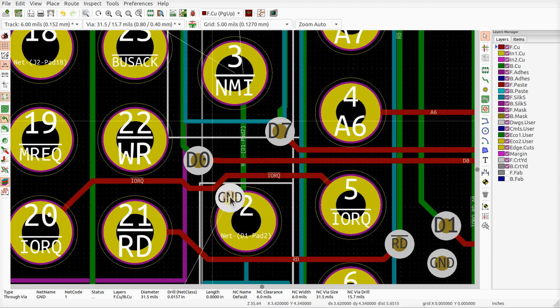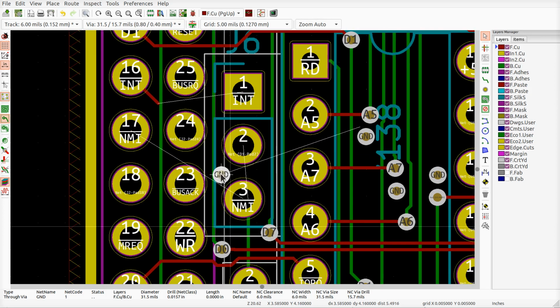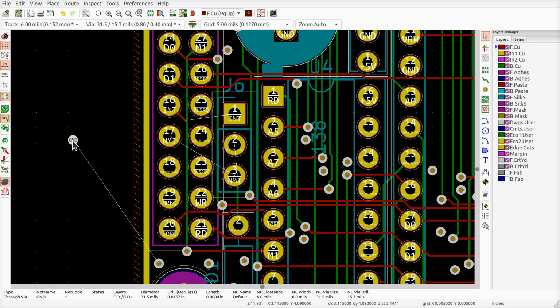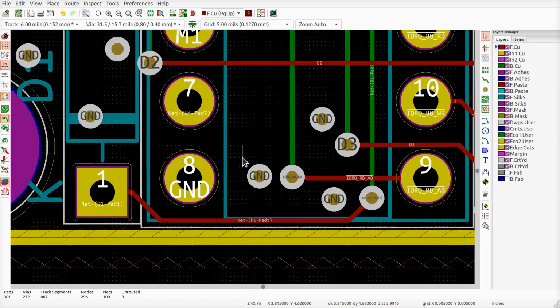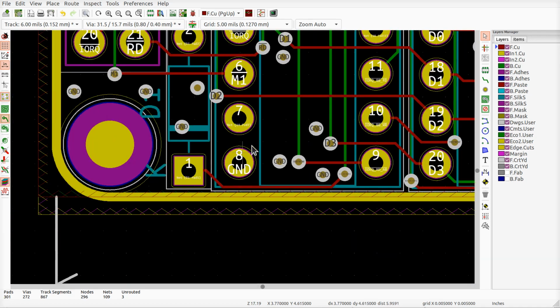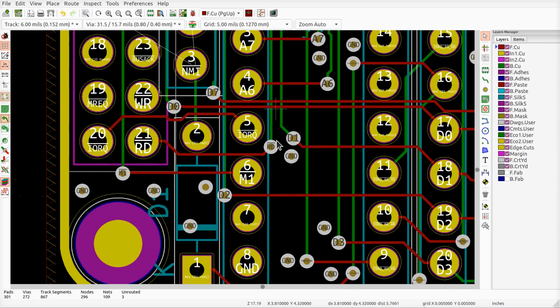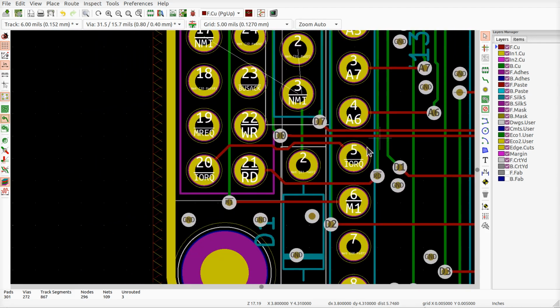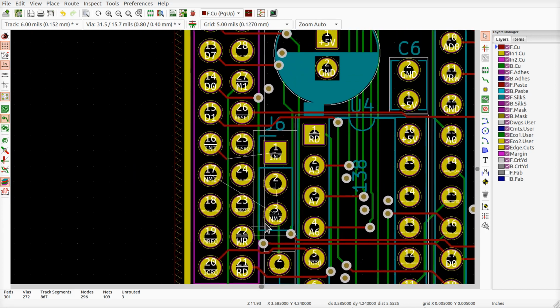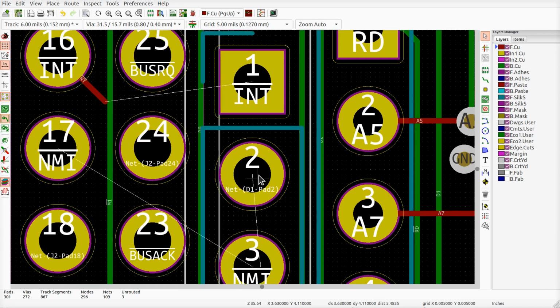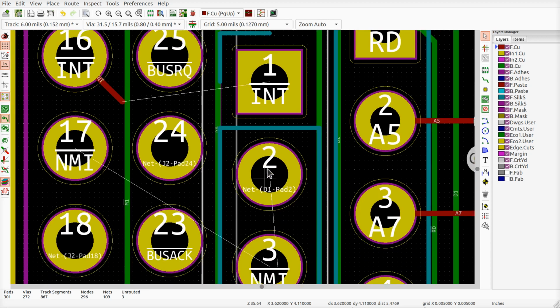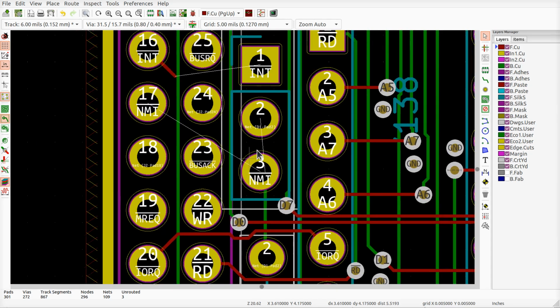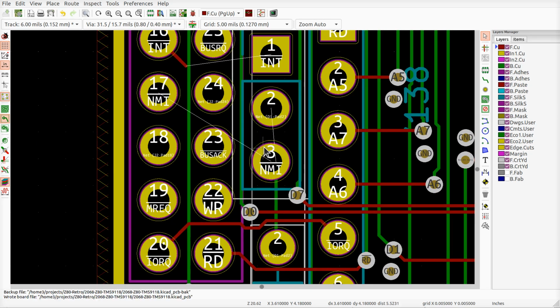Okay. You can go ahead and stick it in a place like that if you really want one. I don't think I care about it. I'm going to delete it. I think the only reason I did it was so that I could add a little bit of copper in this general area. There's a pin right there with ground on it. It'll cause the polygon to flow over there. Yeah, it was up here. I don't know. It's starting to get busy over there. I think we're going to be fine. All right. It was fine before. It'll be fine now, right, people?